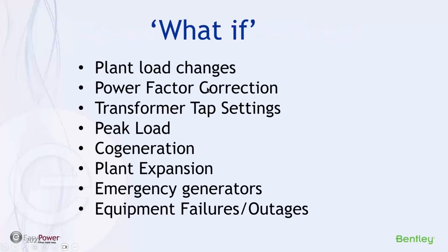Okay, then again, the PowerFlow capabilities can be used to look at what happens when we try to change capacity or move loads around to different parts of the system. The ability to improve tap settings or adjust peak load conditions. The ability to say what if's going to happen if we have cogeneration online.